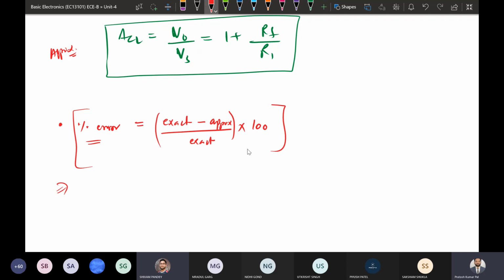If both the inputs are applied with some voltage, that configuration of the operational amplifier will be called a differential amplifier. We are having the input at both the terminals, so that will be differential. In that case, we will get the analysis by utilizing the superposition theorem.